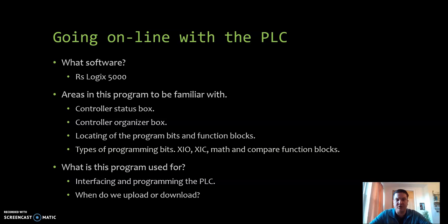You could also see the hardware configuration where it shows you the CPU designation, which is typically slot 0. And then we have in slot 1 our discrete inputs and outputs, slot 2, which would be our analog inputs and outputs, slot 3, which we have our internal counters, and then slot 4, which is our remote or external card, which is our HART communication card, which again, HART stands for Highway Addressable Remote Transducers.